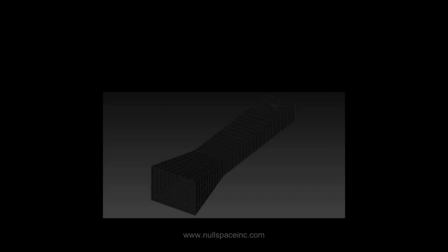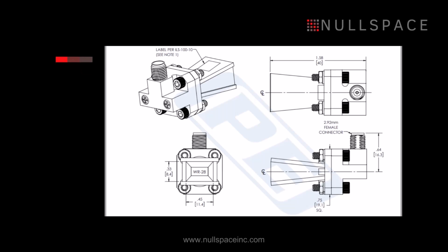This example targets a WR28 10dB standard gain horn. The manufacturer provides a step file for this geometry. However, the detailed feed structure is not provided since this is typically highly proprietary. There is also quite a bit of geometry that needs to be removed, as it is not impactful to the simulation. The goal is to construct a model capturing the horn antenna geometry and couple it to a suitably designed coax to waveguide launcher. The frequency range is the standard WR28 band, 26.5 to 40 GHz.